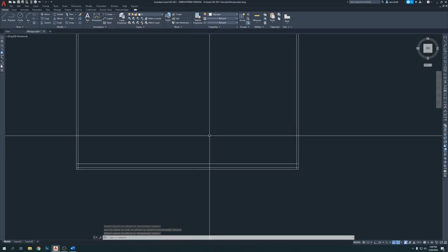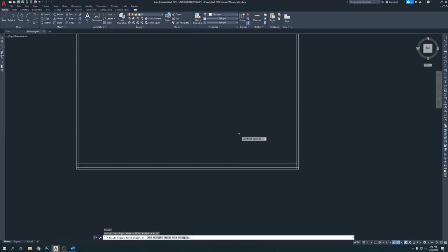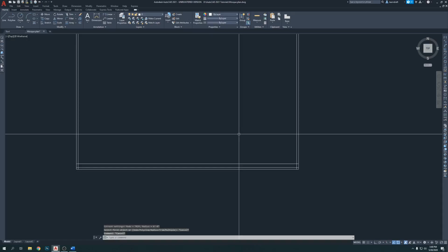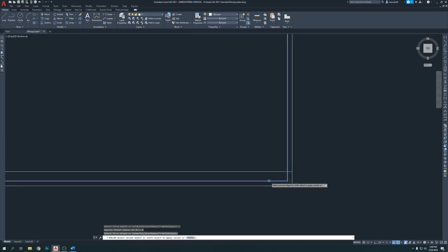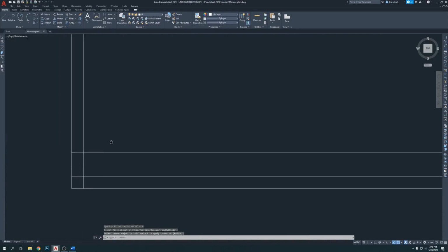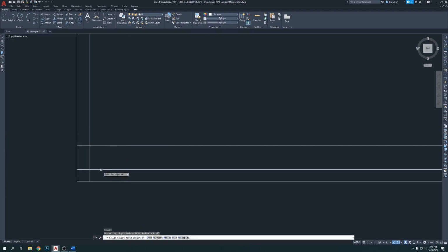okay, we're going to make a fillet. Enter. Radius. Enter. 0. Maybe it selected something else. Oh, I think I'm doing this very fast. Okay, fillet. F, enter, for fillet. Okay, from the beginning. Radius, enter. 0 is selected, but I'm going to put 0 again. Enter. Now I'm going to click this line and this line, so the extra corner line goes away. It's like trimming, but I love to do it with fillet. So the same command, just press enter to repeat the command.